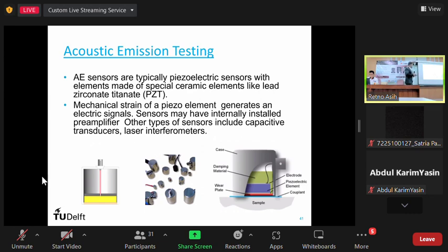And there are different types and versions of the sensors that I have tried to show some of them here. They are usually working based on piezoelectric properties. And then you have a strain that is applied to the piezoelectric sensor, and that changes the mechanical wave into a voltage output. Now in our research group, we are developing new types of piezoelectric materials that are more flexible and easier to work with and to reduce the faultiness of the sensors. So that's one of the directions we are working.